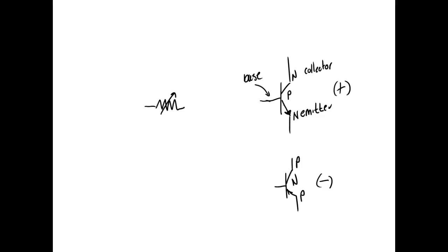Are we okay? So I've got a stereo amplifier that I want to amplify AC. Up here, I would use an NPN and connect it up to plus. Down here, I would use a PNP and connect this up to minus. Then I take my stereo speaker and hook it right there.